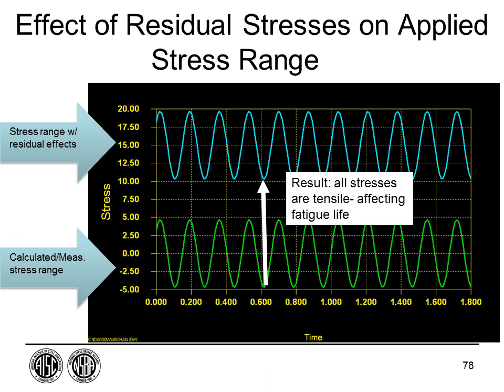Why? Well, let's think about this. If I were to put a strain gauge on the element, or I were even going to make a calculation, but say in the laboratory I'm conducting a fatigue test, and the test is running at plus and minus 5 KSI, cycling back and forth. And I put a strain gauge or I did a calculation, this is the stress I would calculate. But now we know that in that welded detail, there's high tensile residual stresses. So that locked-in effect has the effect of doing what? Well, instead of part of the cycle being compression or minus 5 KSI, and my mean stress being 0, my real mean stress was 15.